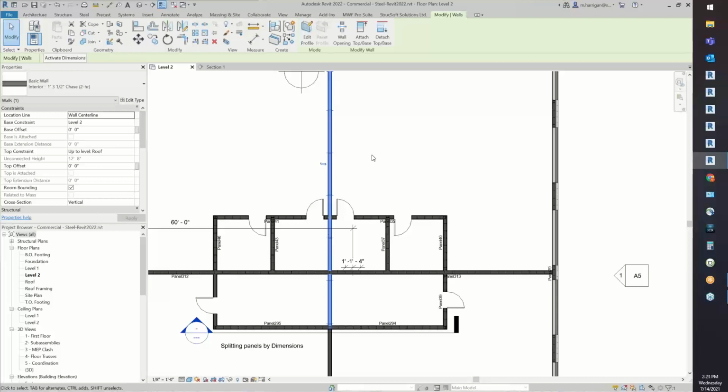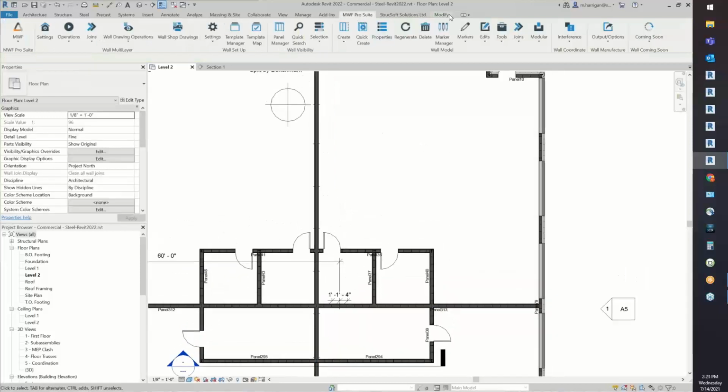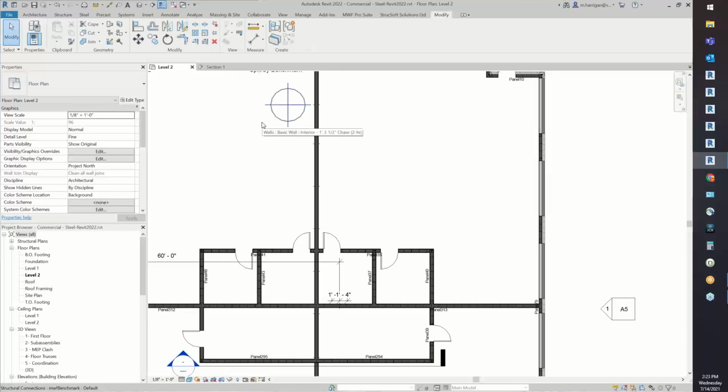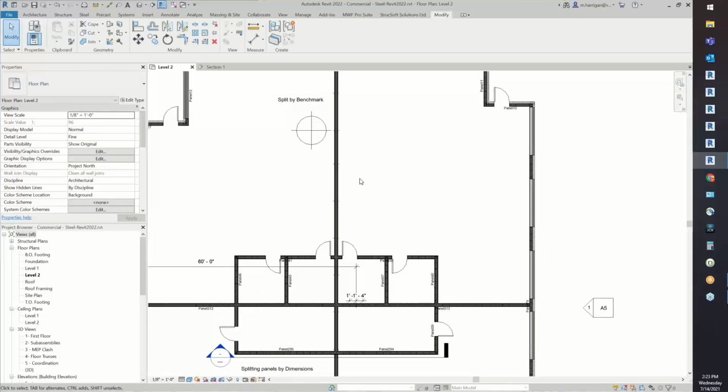From there, when it comes to our multi-layer, the concept is one panel, one wall. In this here, we have the one wall, multiple panels. So what we need to do is split this wall into sections of the maximum of what we can do. So we can use the splice of Revit. However, in this case I do have a lot of splices. So what we have done is we have created a tool that will splice your wall or cut your wall at each split marker. So I'm going to select this one here.